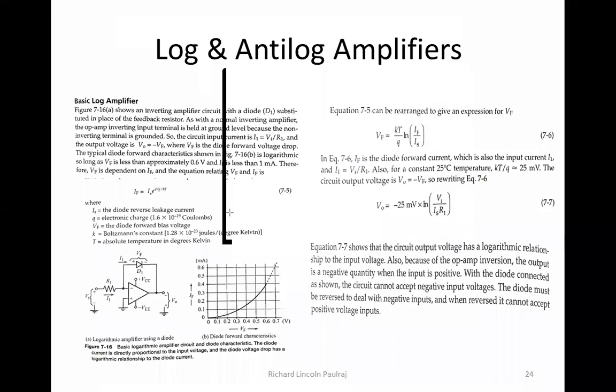That's right. Since the positive terminal here is at ground potential, the op-amp will make sure that the other terminal also has the same potential. That is nothing but the virtual ground concept. And this is going to be an inverting form, which means whatever input I'm giving is going to be in an inverted fashion.